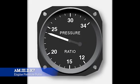So a higher EPR can indicate better thermodynamic efficiency, but design and operating conditions matter. So that is EPR. You'll generally see this referred to in flight manuals. Generally speaking, unless somebody's got a write-up that reflects this, we won't mess with this too much, except for dealing with the pickups primarily. They'll go out. You'll end up having some kind of crazy ratio that everyone knows is not right, and it's typically going to be wiring or instrumentation somewhere along the way.